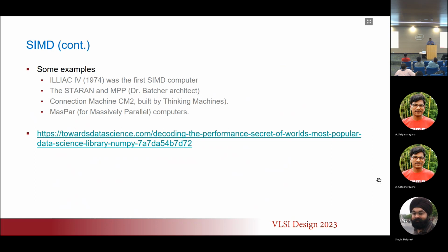So when I fetch the data, and I've fetched one tile of data on my input, and I'm doing multiple filters in one cycle, in one clock cycle, I'm able to do convolution on that input data against 64 divided by 9. Okay, so that's like 7. So I can do 7 filters at a time.